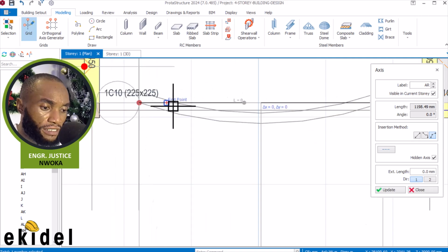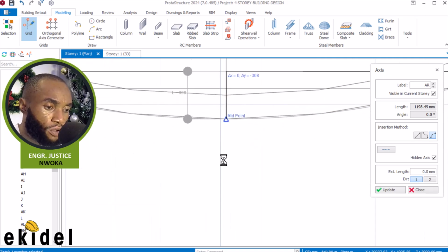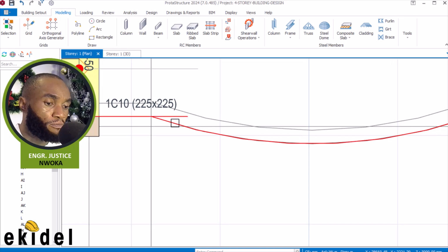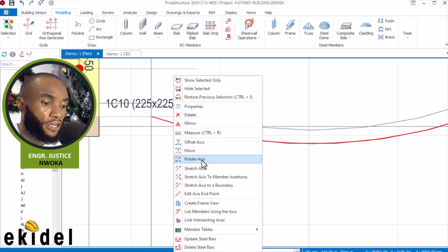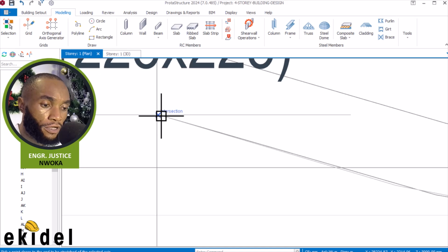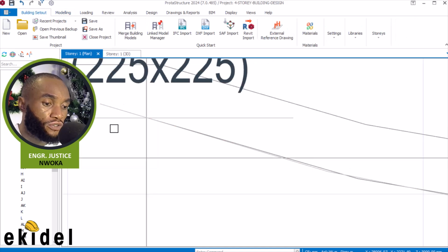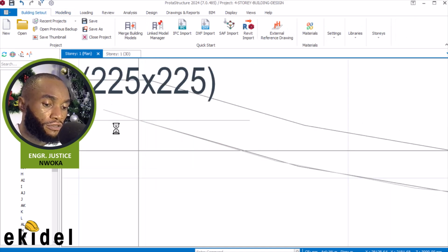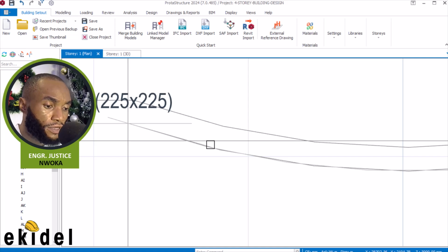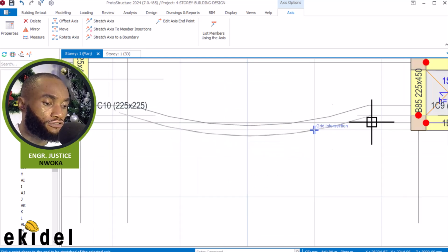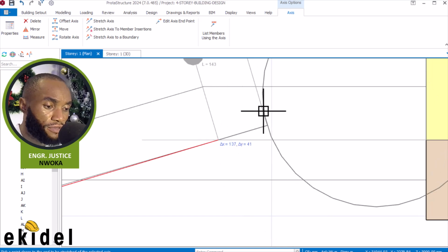All right, that's fine. Then click on the chord, on that point. That's fine. Then escape, and make sure I stretch that curve extension point off the boundary for the slab. Click on this here. That's fine. Again, the other side too. Click on the slab again. Right click, sorry, on the line. Right click here, which is the grid line. Stretch. Correct. That's fine. Click on this, stretch out a bit.